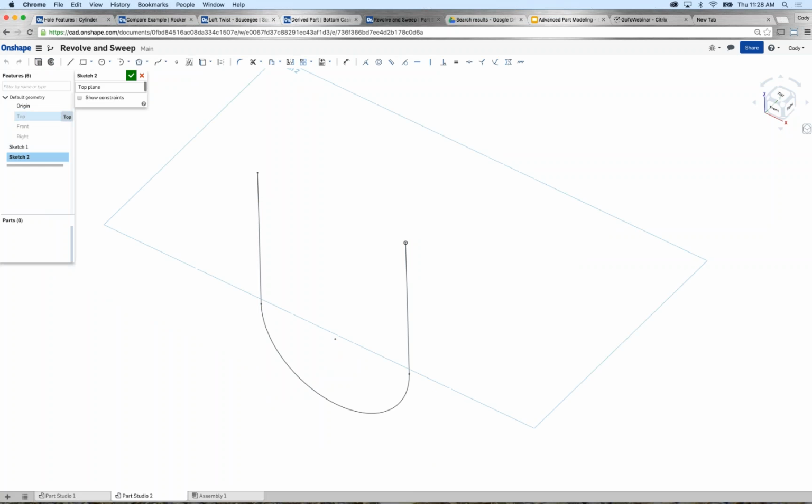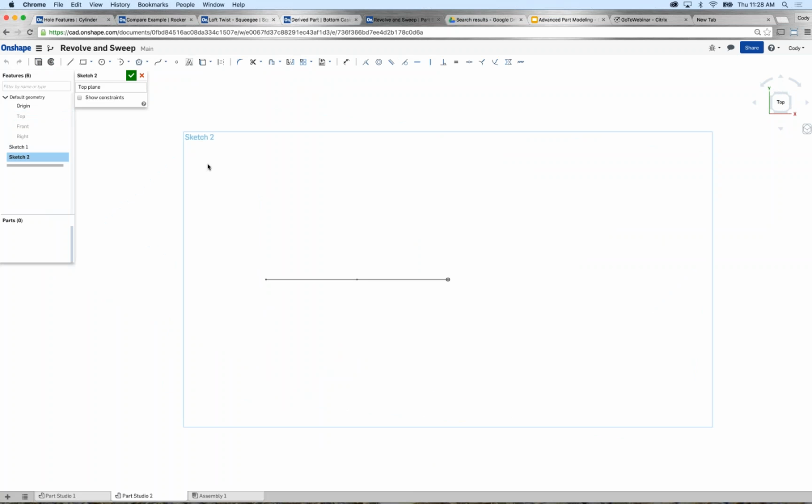This is our profile. And in my case, if you think about a U-bolt, it's really just a circle swept along that U shape, right? So we're going to draw a circle. I'll attach it to the origin here. Actually, let's deliberately bring this out. Okay, and I want to dimension it. Okay, we'll add a 0.5 dimension.